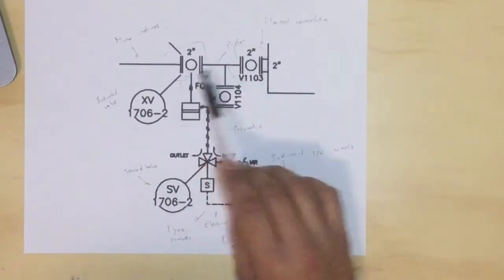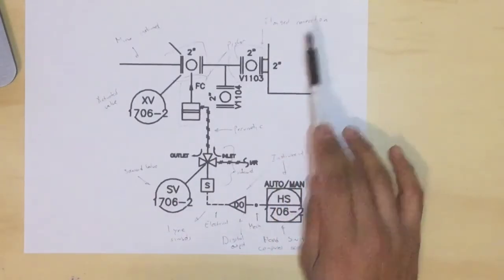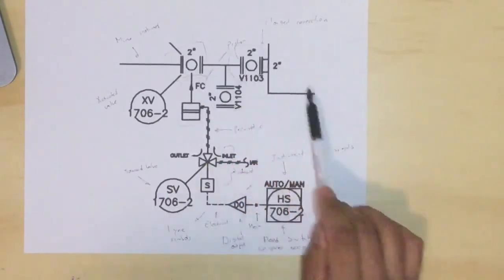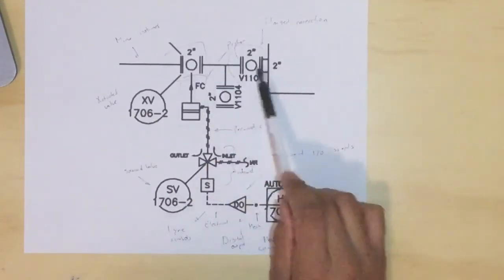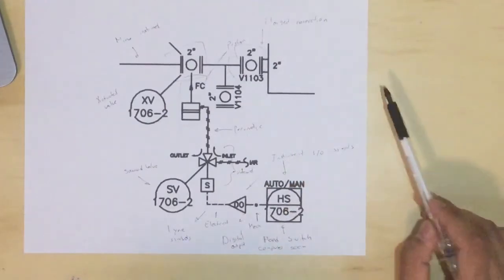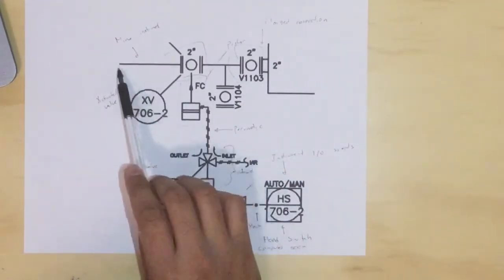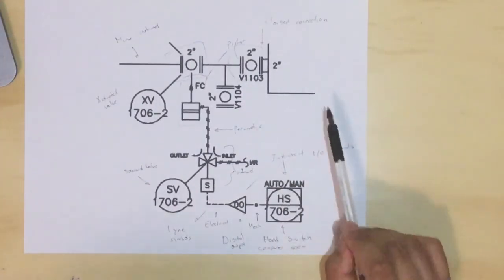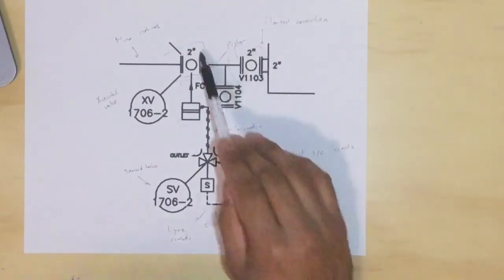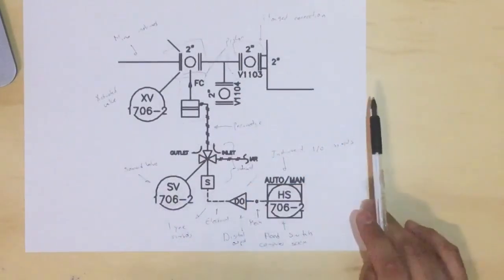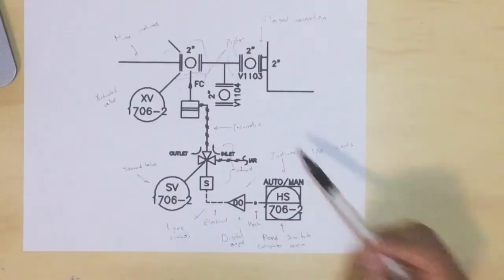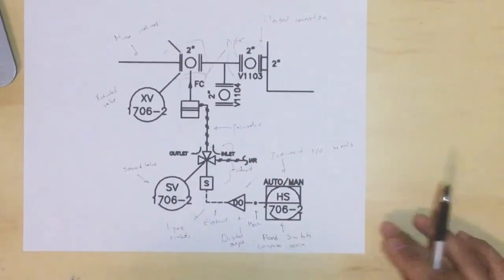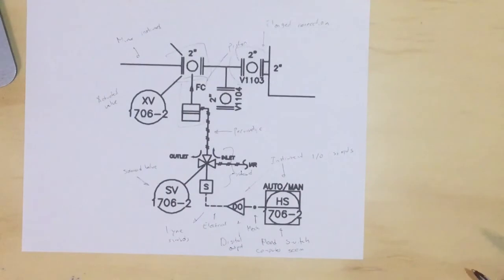This valve is a kind of flanged connection valve, and it goes to minor instruments and is connected to other processes. Here we have three different valves. These three valves are flange connection valves. We have this minor instrument signal, and these two numbers are the diameter of our connection. There are 2 inch connections, and this is how we analyze our types of PIDs.